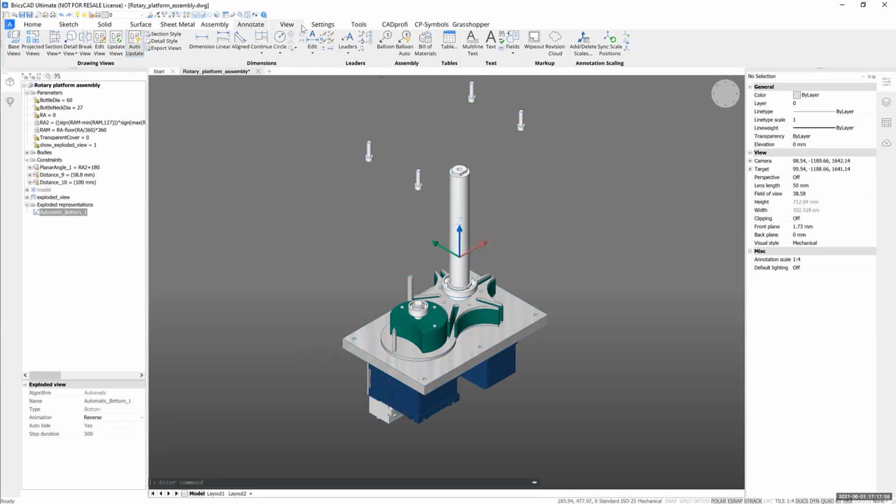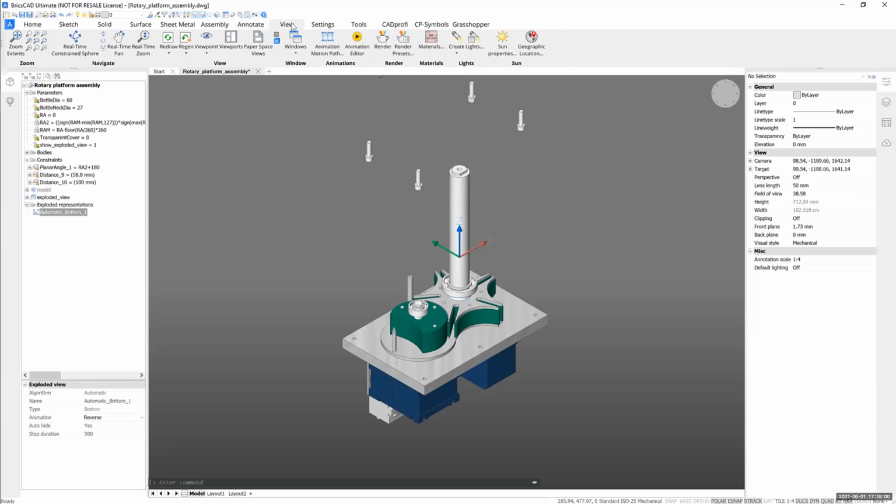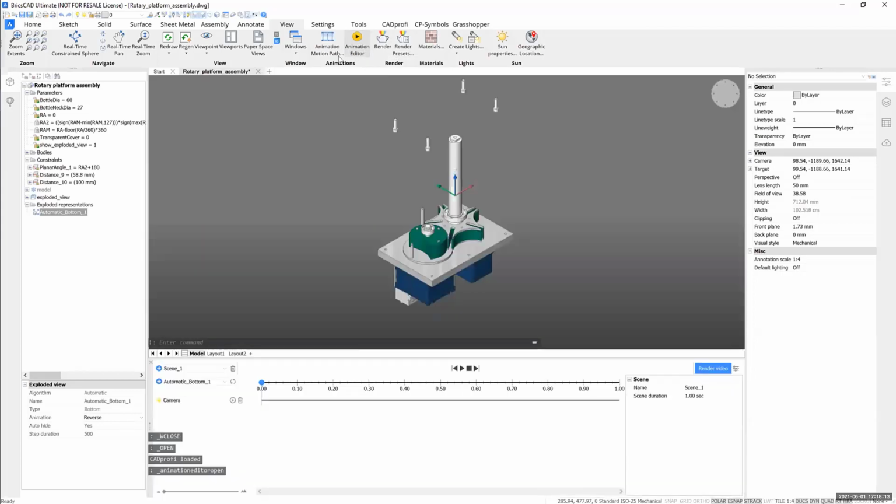So to start working and to create an animation, we can go to the top of the screen on the ribbon under the view section. Here you can see the yellow play button called the animation editor. And this will open an animation panel. By default, it should appear on the bottom of your screen. And this is where we will be manipulating and creating timelines to interact with these parameters.